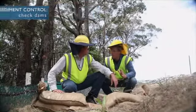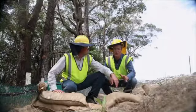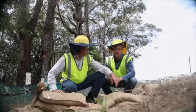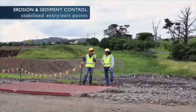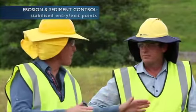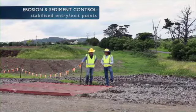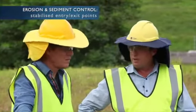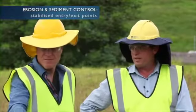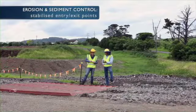So installation is paramount. What about the entry and exit points to minimise erosion and capture sediment? Let's take a look at that. So when we say entry and exit points, we actually mean coming in and out of the site, like here. Yeah, that's right, Pete. So the entry and exit points for our sites can be another high-risk area. They can erode themselves, but also we've got a lot of truck movements coming in and out of that site. And mud attached to the tyres of those trucks when they leave the site can actually get tracked a fair way up the road.